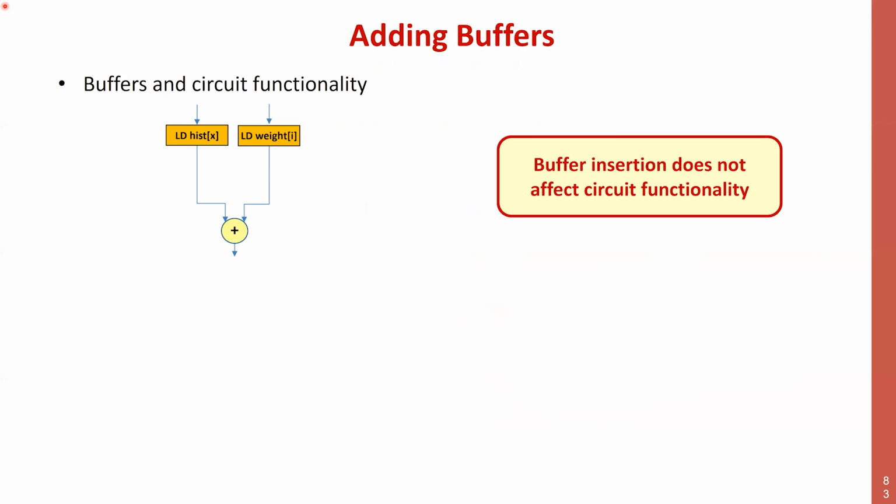The first thing is that buffers don't behave exactly like registers in our classic synchronous design. So imagine that you have the circuit that you see here, and you now imagine that you want to put a buffer here. Now, I hope it is absolutely clear to you that this modifies the functionality of my circuit in the world of standard synchronous design.